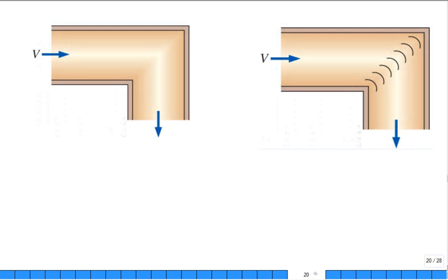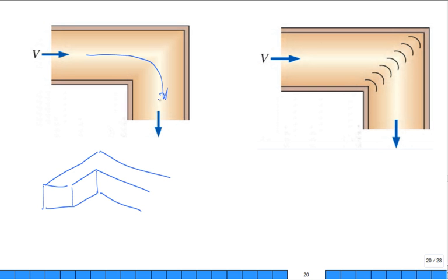A lot of homes have rectangular ducts in the attic that carry the air. They're made out of duct board. They're easy to install. They need to turn at the corner. A lot of times when they install them, they turn a corner, and it's what I would call a hard corner. If you own an older home, you might want to look up there. You either have flex duct, round, or you have duct board, which is rectangular. Looking down, it's really hard for the air to navigate that turn.